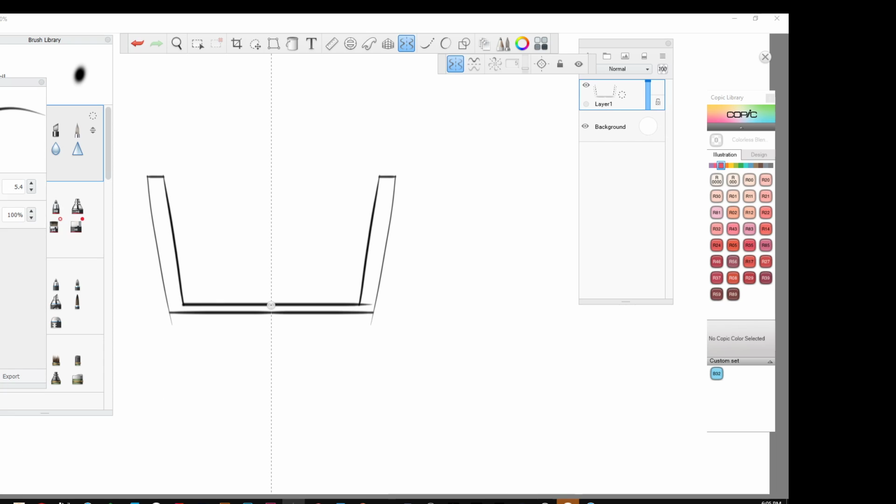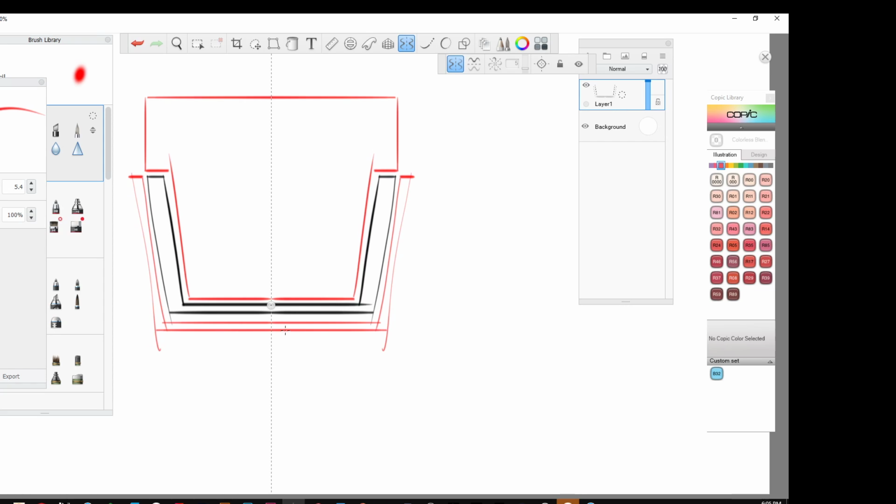So you want the part to come off as easily as you can, because you've got tooling that goes down into the mold. With the red being the tooling part and the black. You don't want it to get what's called hung up. Or what happens too is it can scratch and wear, and you need to repair your tool more often, and tooling can cost $500,000. So you want to design it so that you're not having to repair it every year. Especially when you think about some tooling and some volumes, like injection molding, you're running 1,000 parts a day, or you're running 100 parts, whatever. So every time that machine is down, it's costing you money.